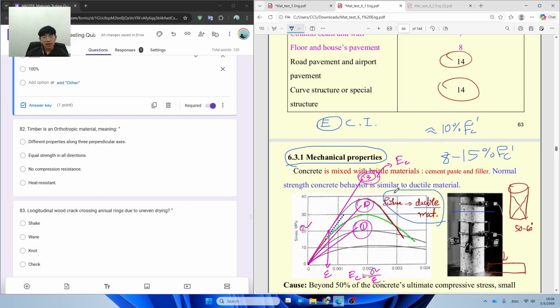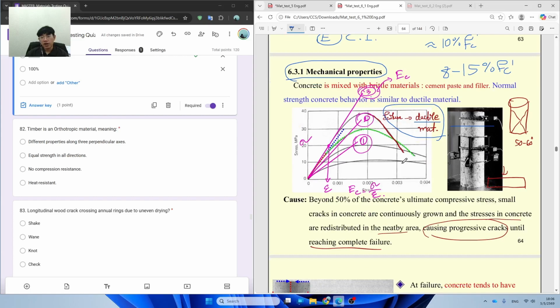When you put in less water content, you are going to get a really high strength of the concrete. When you obtain such a high strength, your modulus of elasticity is also high. And if in the examination I ask you to find the modulus of elasticity of the concrete and provide you this curve, you must be able to find it by drawing a linear line straight on the curve over here and then picking a point in the linear zone, using Hooke's law to find the Young's modulus of elasticity using stress over strain for the concrete.